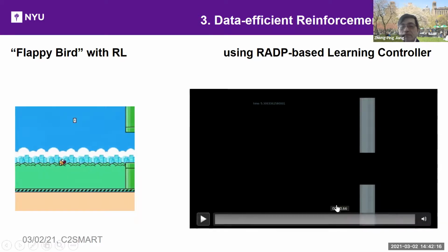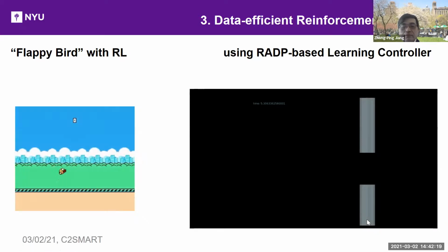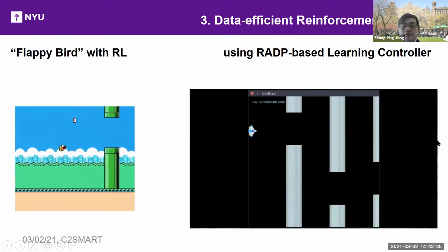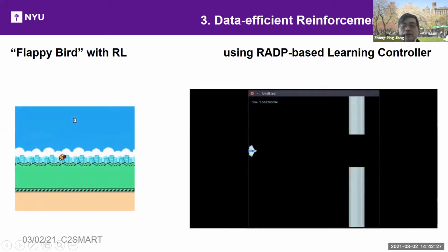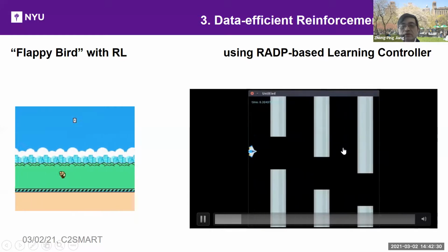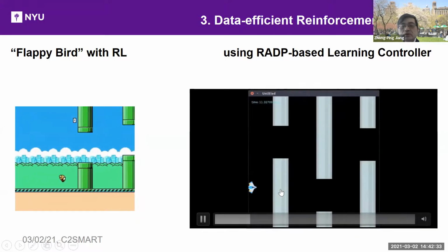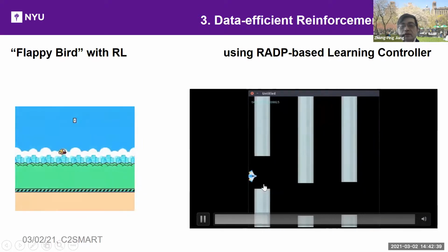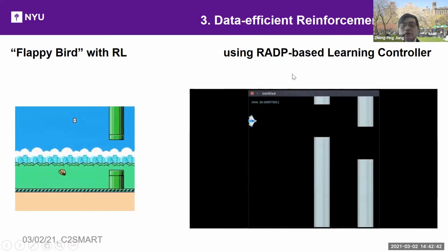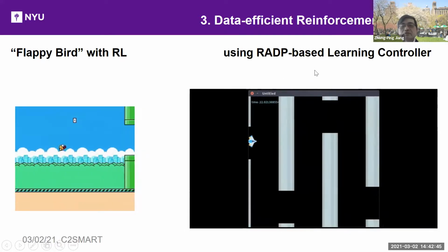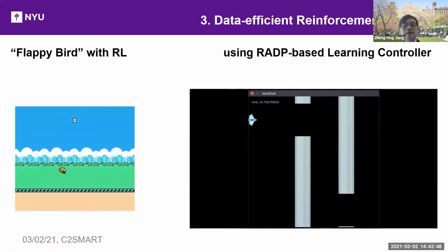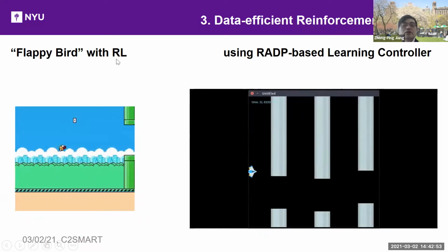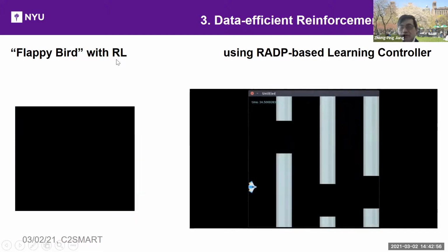But for our video, you're going to see that it is much faster. It converges in less than 10 minutes. Occasionally it's going to touch obstacles, so it's going to fail, but we can use the data, start over, and update the controller. So this is a difference. It's not totally model free. Our learning-based controller uses techniques from dynamic systems and control theory. That's why it has much better performance than the traditional model-free reinforcement learning approach.